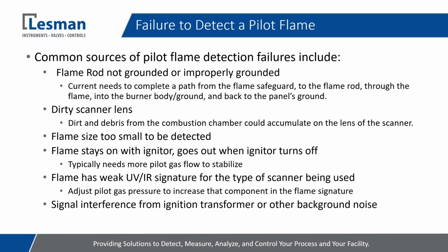So you can maybe see the flame visually, it's occurring, but maybe it's just too small or too weak for the flame detector to detect it. So it just would mean that you're most of the way there. You just need to tweak your pilot gas or your airflow.